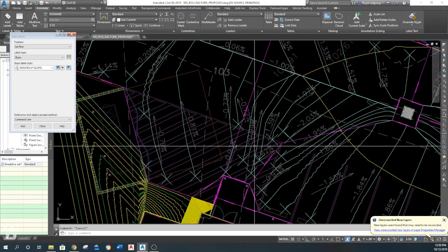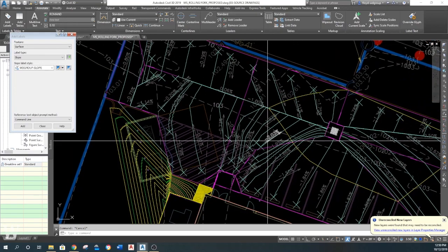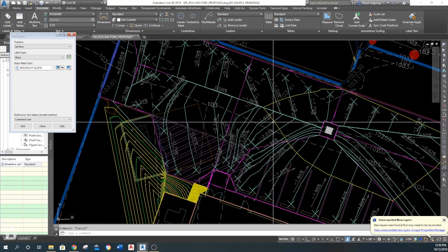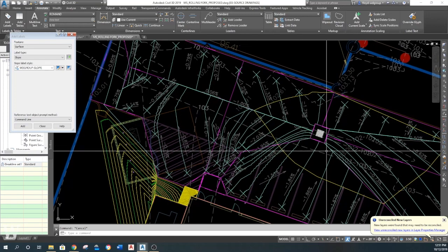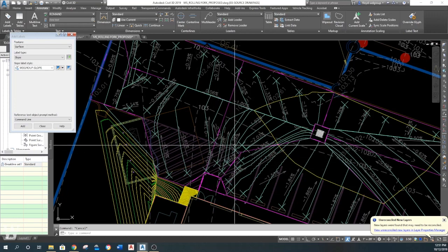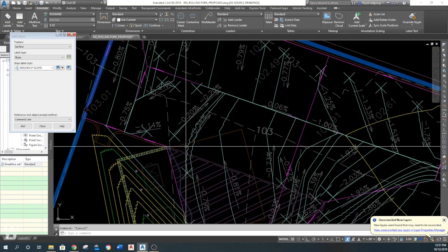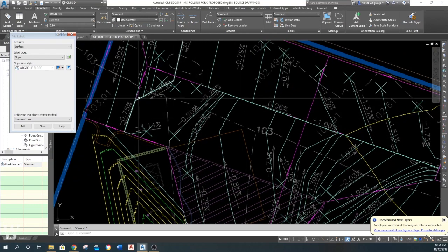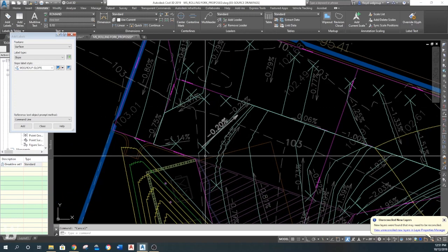The only thing I have is I'm a little bit steep right there, because it's not too steep for a parking lot. Family Dollar really doesn't want this over 1.5 or really 1.5. They'll leave it with 2. We usually wind up with some of that in 2. This area right here in the loading dock, they don't want too steep. So I've got to make a little bit of a change right here. And it's flat right in here because what's happening is the water's trying to decide which way it wants to go. So I need to go clean this corner up.